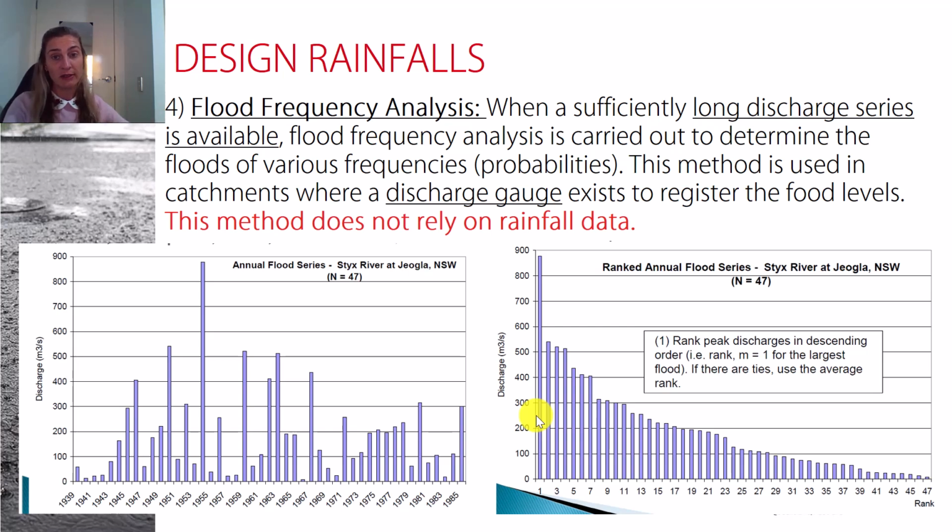for a smaller catchment. Okay, there is something called regionalization, which is when we transfer the observed discharges from a large catchment to another catchment using some parameters to correlate the two catchments. Then we can sometimes transfer those readings to a smaller catchment using some parameters to make this adjustment. Okay, so this is called regionalization. We're not going to be looking at regionalization in this course, but this is possible, and it's very important that you know and you're aware of this method as well.